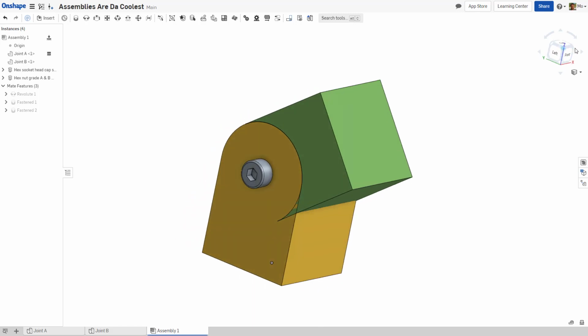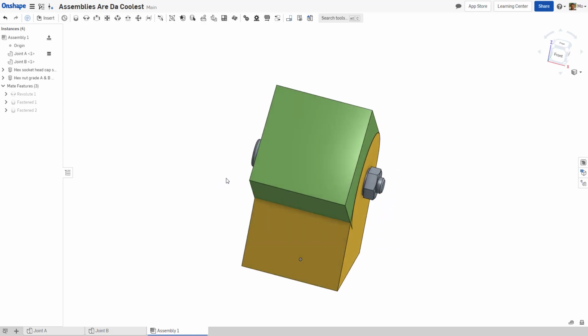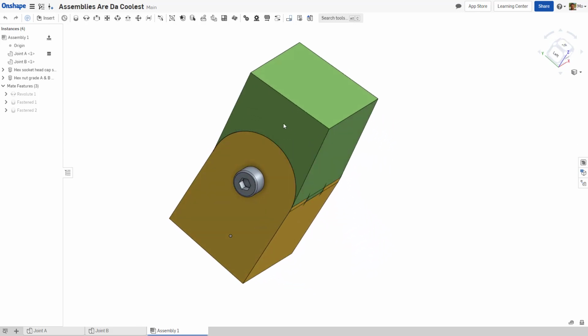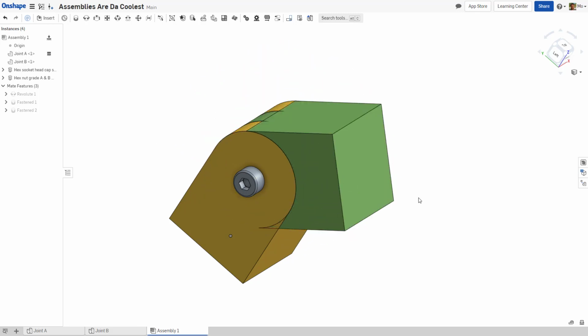In our next module, we'll address this issue with tolerancing. We'll eliminate the overlap between our two joints, and we'll create some space for these parts to move around freely. We'll also create a counterbore for our hole, which will allow us to recess our nut and bolt axle.